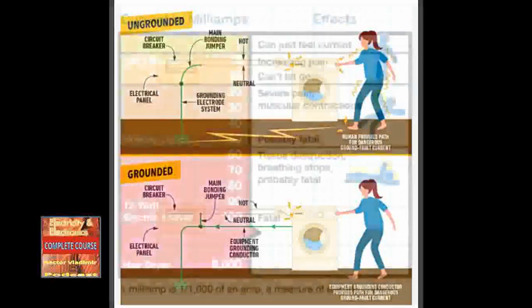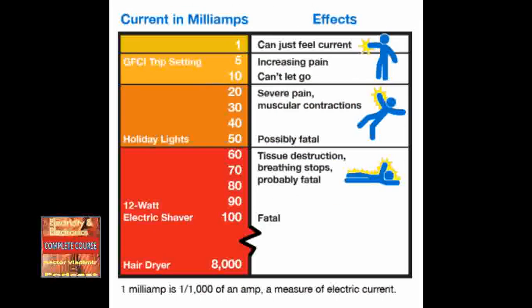Electric shock levels. A person can experience different levels of electric shock. These are rated by value of current flow and the effect each current value has on the human body. The values of current flow and their effects are listed in the following table. Current, 1 milliamp, is barely noticeable. The current of 5 milliamps is the highest harmless value, but can be painful.